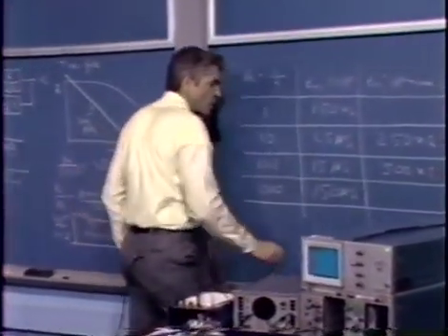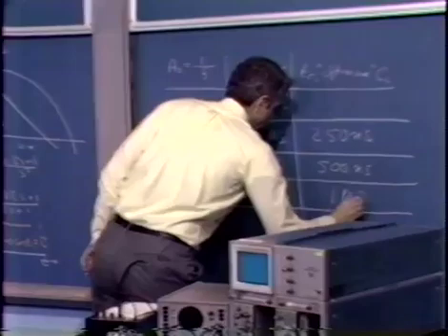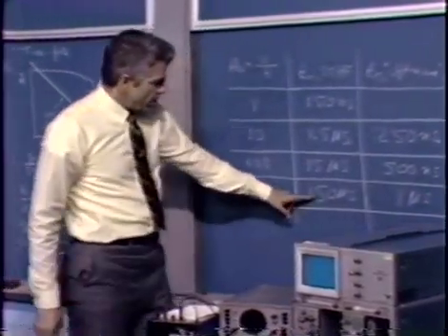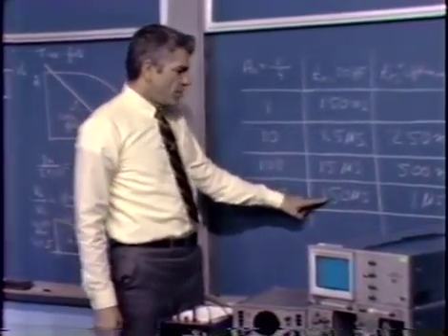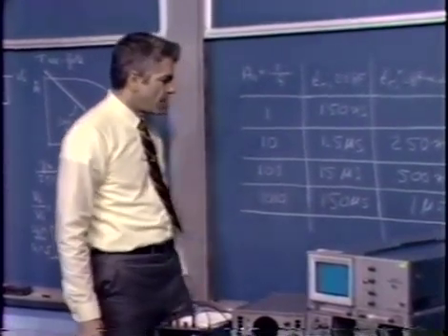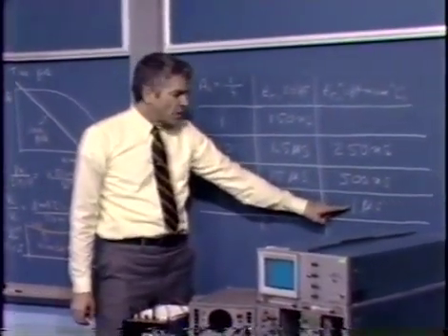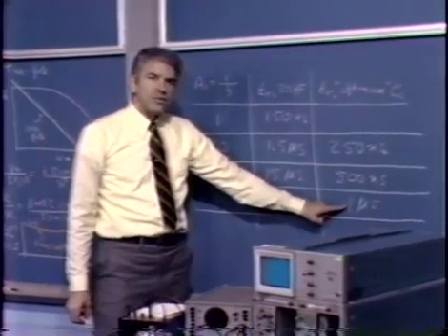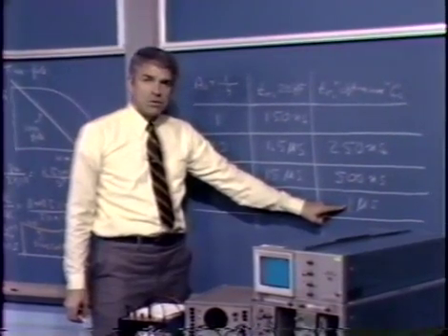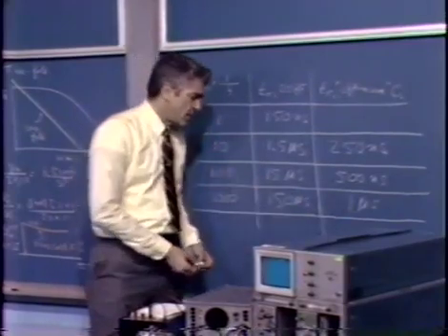So we get about a 1 microsecond rise time, roughly a factor of 150 to 1 improvement in rise time and correspondingly bandwidth. When we compensate with this small value of capacitor, we still have something like a 350 kilohertz closed loop bandwidth at a gain of 1,000.